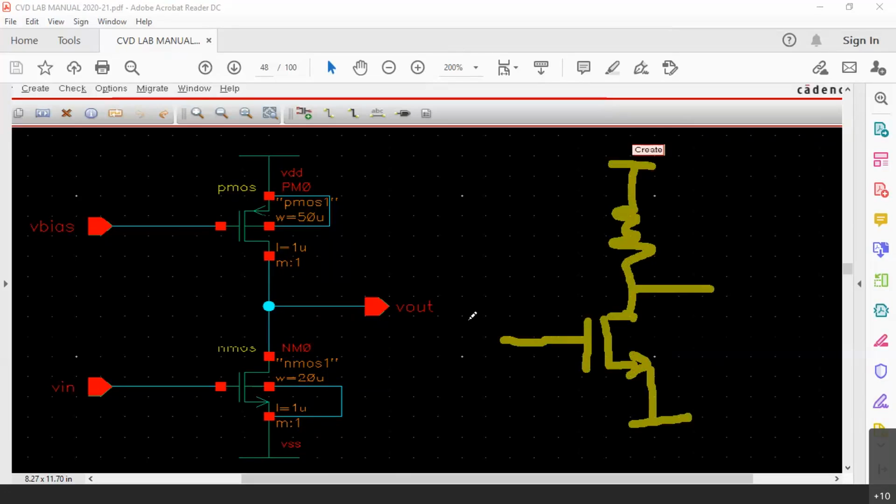Now, you are seeing a circuit at the right side. I had already shown you a resistance at the drain, which is required. Now, the output coupling capacitance we are leaving out in this case because we are only measuring the direct output here. If you want later on to couple this amplifier to the next stage, we can always put a coupling capacitance there. That is no problem.